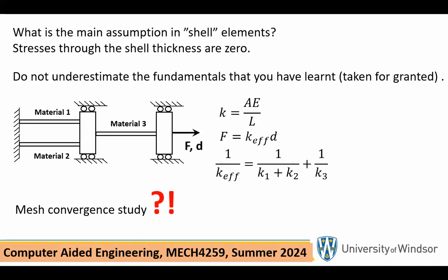You make a finite element model of that thing that you made and run it. You have no idea whether the numbers are actually depending on the size of the elements used. So that's what I mean by mesh convergence. In other words, now you run it again. If you have access to a better quality element, use it. For example, if your initial run was in linear elements, for the second run, I suggest you do it in parabolic elements, more sophisticated, and compare the results of the two.